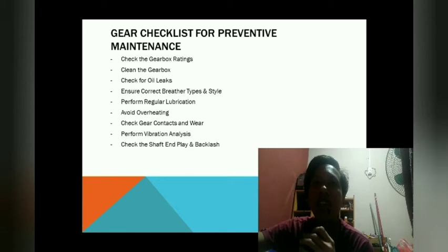Next, check gear contacts and wear. At regular intervals of usage, you should check for the possible wear of a gearbox. Also check whether there is any misalignment of the contact between the gear teeth.